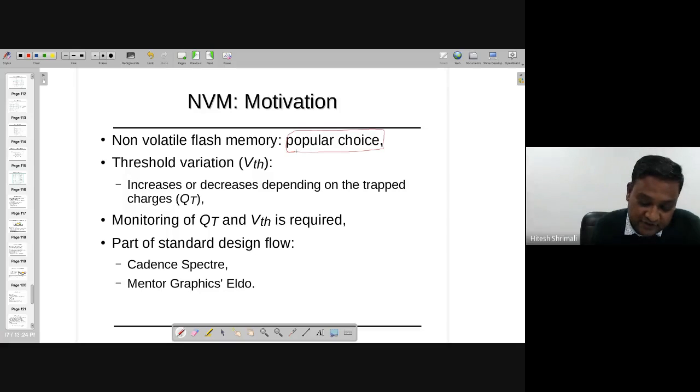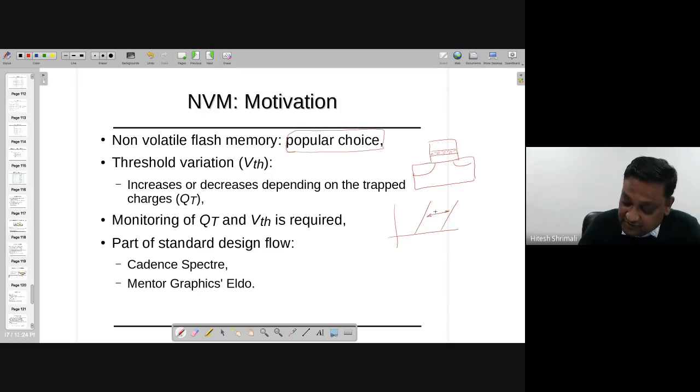And when you're doing this, you can understand now, if you can relate with the diagram which I showed over there, that when this particular gate is empty, it's a low VT. But when it's filled with electrons, it becomes high VT, and you cannot actually read logic 1, right? It will be logic 0. So VT is going to shift, and this delta VT,